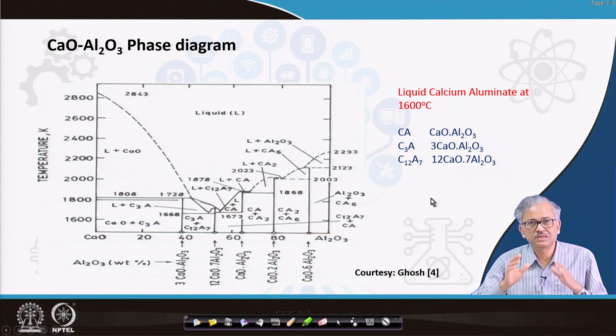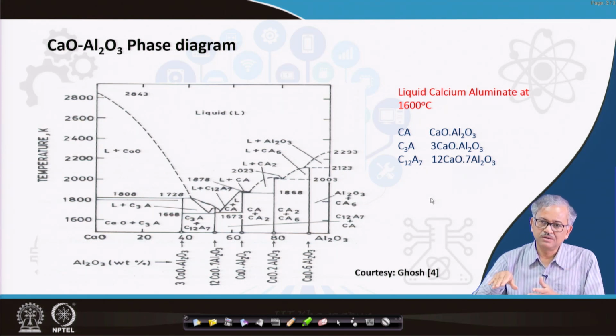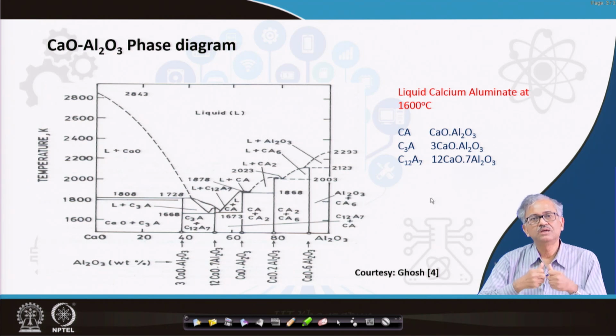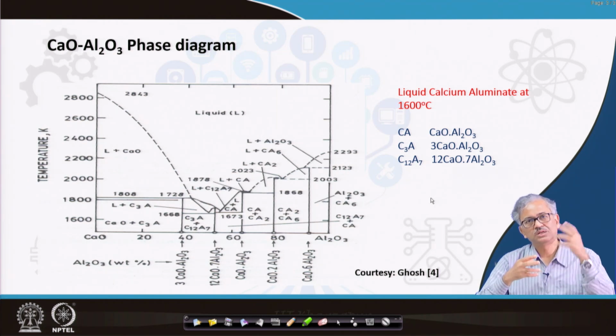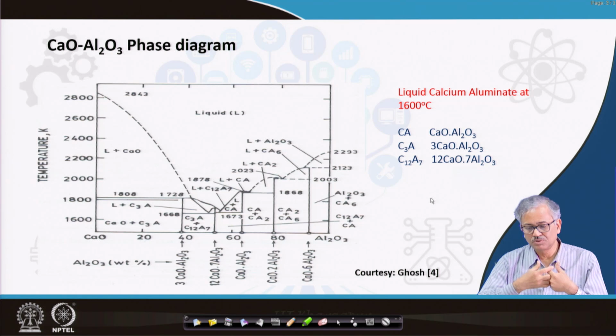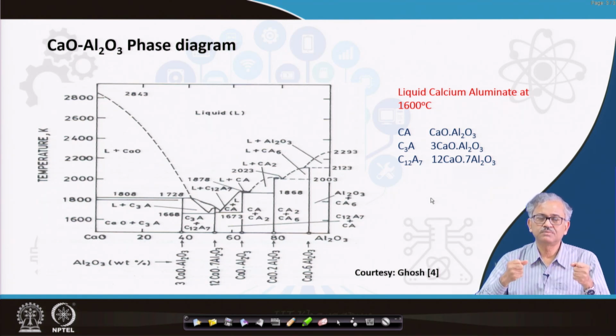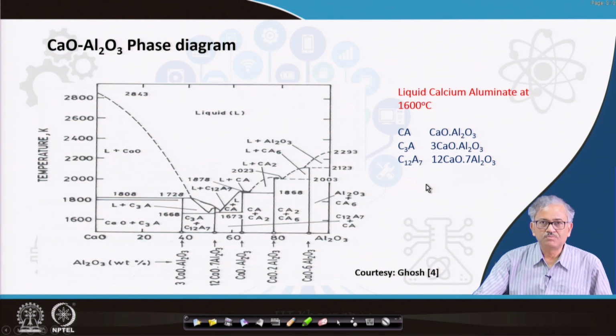So calcium treatment does two things. One is that it produces a liquid product of deoxidation, calcium aluminate; some of them are liquid. As a result, you can get rid of nozzle clogging. Besides, the liquid inclusions can coalesce and form bigger inclusions and go away from the system. And those inclusions that cannot be removed from the system can also be converted to soft deformable inclusions. So that is possible by calcium treatment.